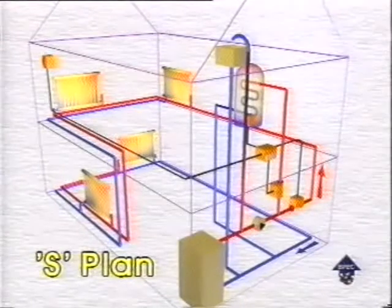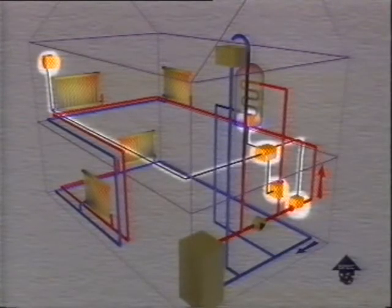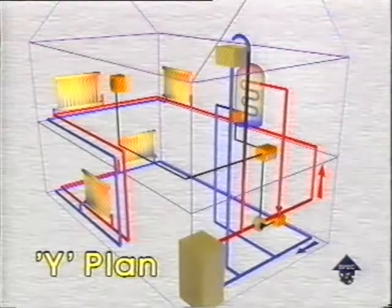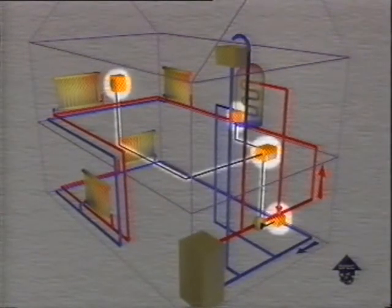Other systems don't rely on gravity, but use a pump to circulate hot water to the cylinder and radiators. This is the S-plan. It has two-port motorized zone valves, which are controlled by thermostats on the cylinder and in a room. The Y-plan uses one 3-port valve, which again is controlled by two thermostats. Because this valve is a flow-sharing type, the Y-plan's suited to smaller central heating systems.